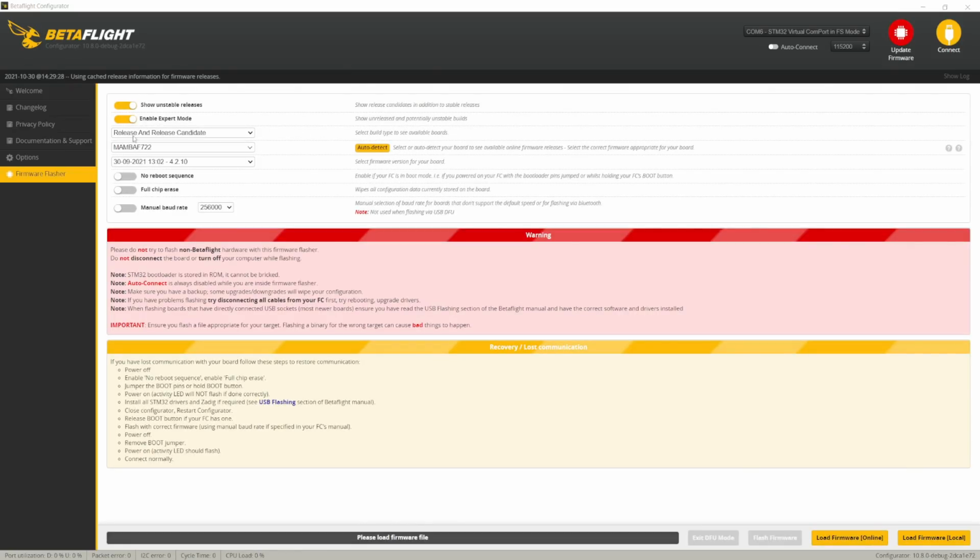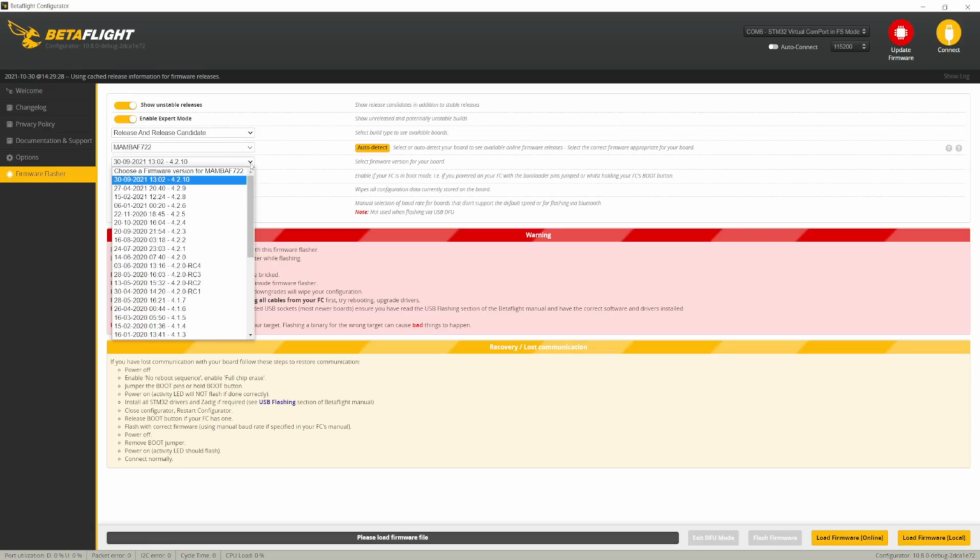You're going to go and select Release and Release Candidate. You're going to choose the board name. For me, it was Mamba F722. And then you're going to select the latest build of Betaflight 4.3.